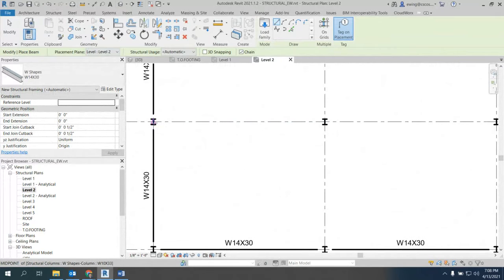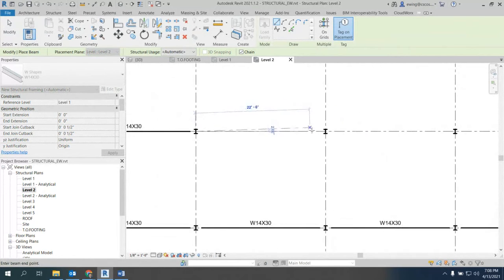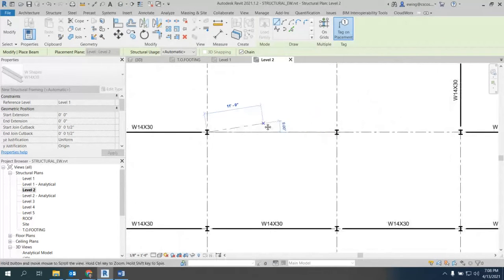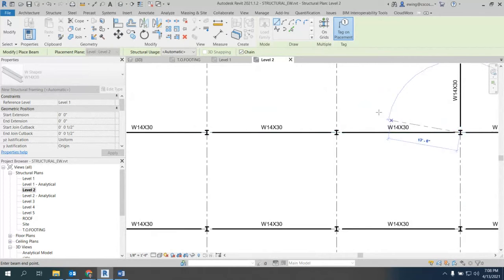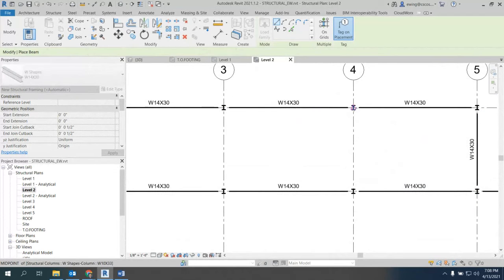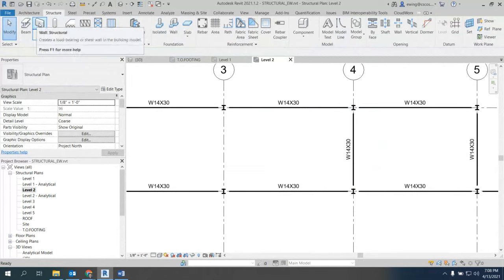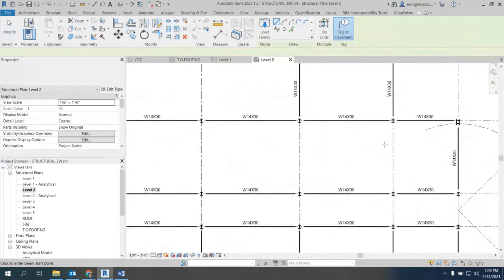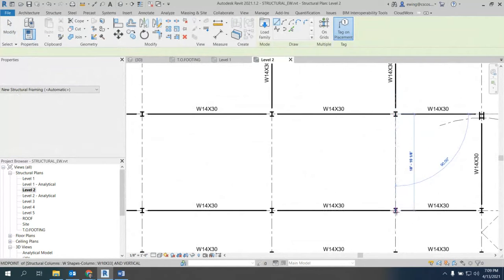Like if you mirror it, it has the new properties, right? Actually, I guess that's more for columns, but like the A1, A2, and all that. If you mirror, it gains the new properties. It does, okay, yes, cool. The only thing you have to worry about is if you accidentally mirror something that's already in the spot where you're mirroring it to, then Revit's going to say, oh, you got two overlapping items here.